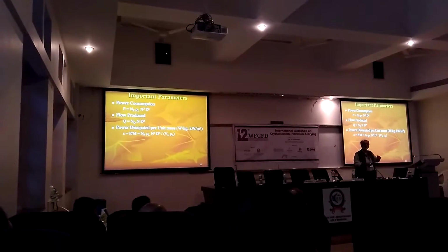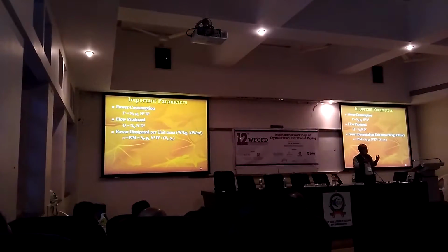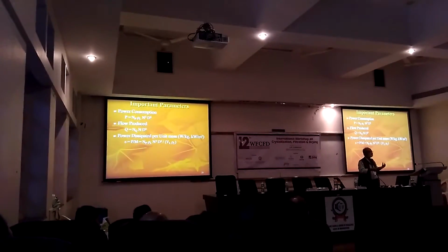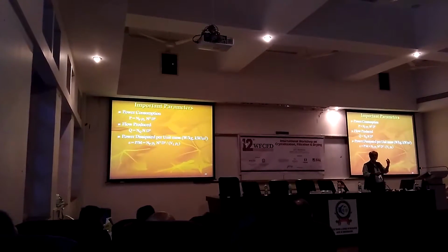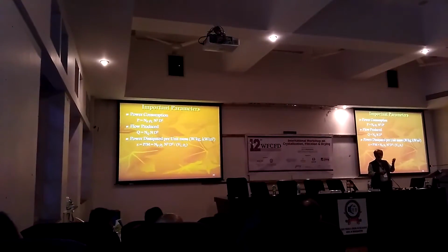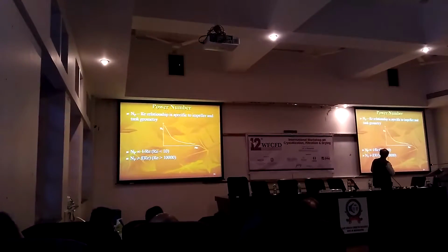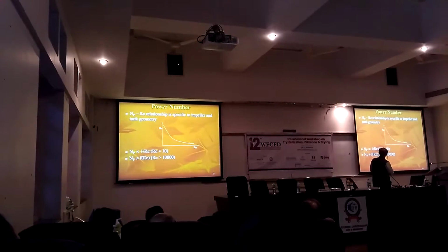So you will find with the increase in the scale up of crystallizer, in fact the amount of energy which is required to keep the solid particles in suspension significantly reduces when you scale it up. Usually people are afraid of that, but they need not be. Right, so this is how you estimate the power number.